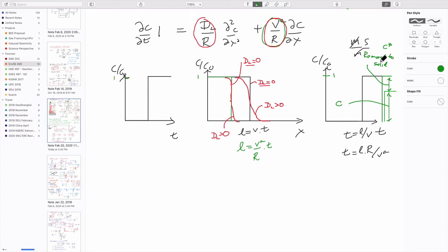So you'd expect to see these two things. One is it is retarded, delayed, so it goes less far in a given time, and to go a given length to come out of the end of the aquifer, it takes longer to get there, which is embodied in both of these plots here. And because the effective dispersion is reduced, it becomes sharper if it's retarded.